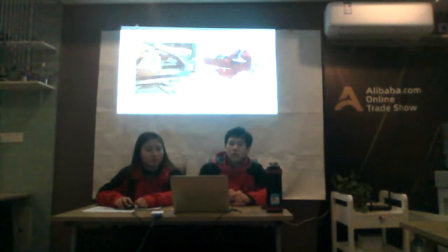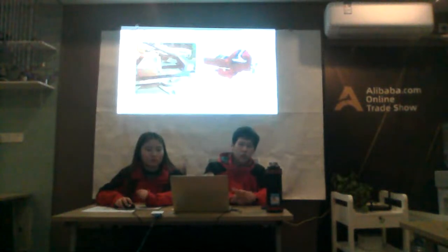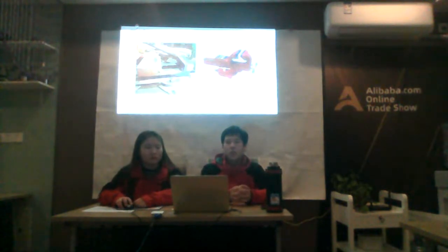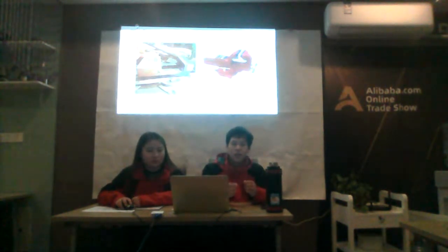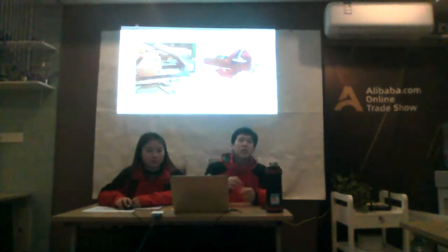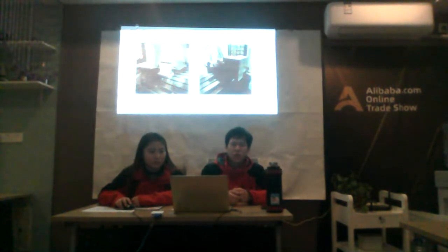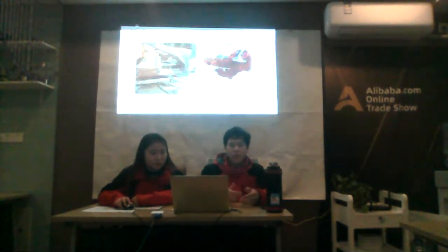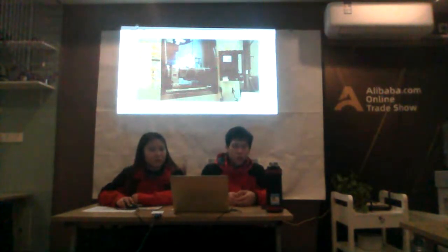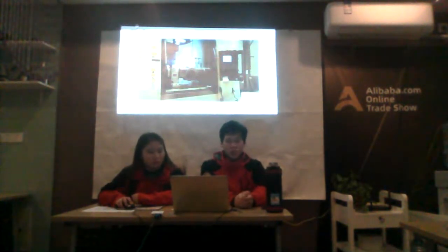And this is another approach if the customer wants to process their workpiece in a horizontal direction. It's called the vise, which we get from other suppliers as well. The vise is equipped on the work table, and it will clamp the workpiece at the center of the two clamping sides, and we process the workpiece with the spindle. It's used for some small components, not as long as the workpieces for which we use the 4-axis rotary.